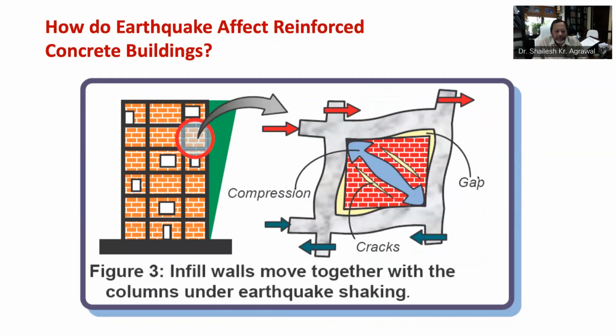After columns and floors in RC buildings are cast and the concrete hardens, the vertical spaces between columns and floors are usually filled with masonry walls to demarcate a floor area into functional spaces, that is the rooms. These masonry walls are also called infill walls and they are not connected to surrounding RCC columns and beams.